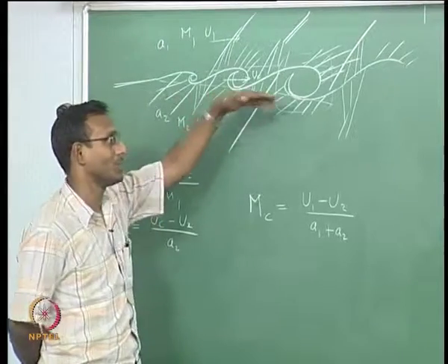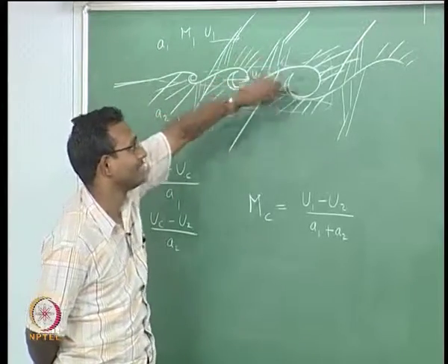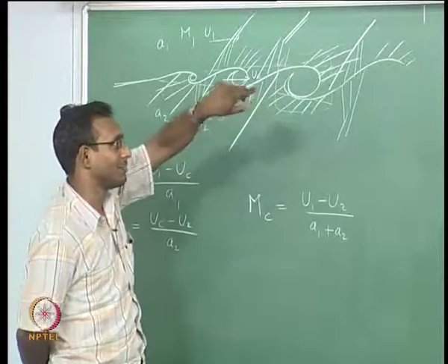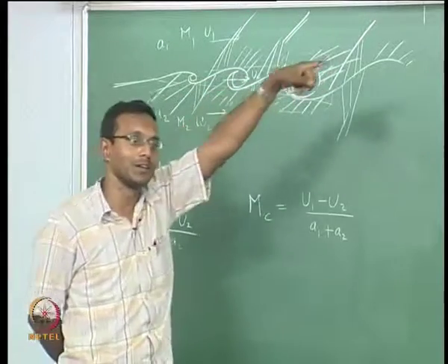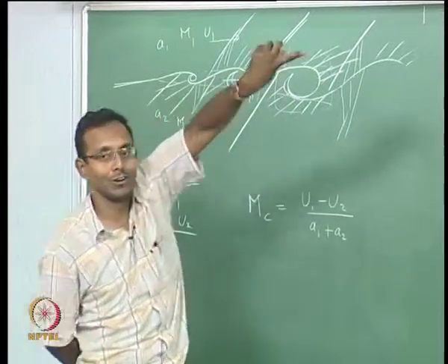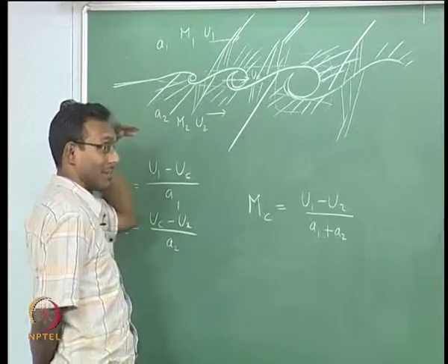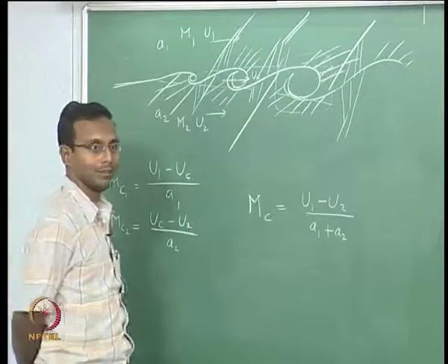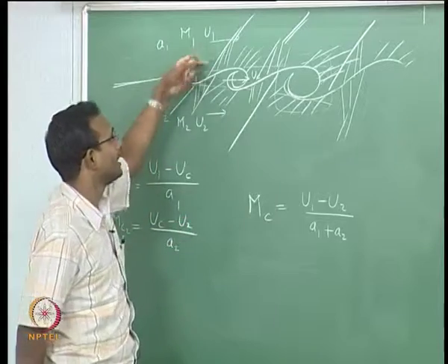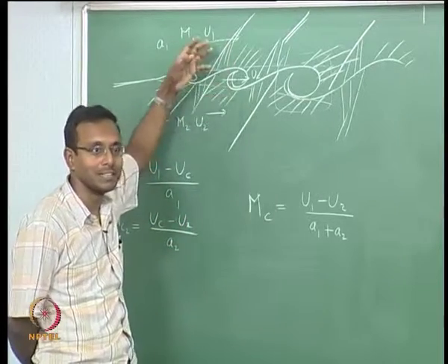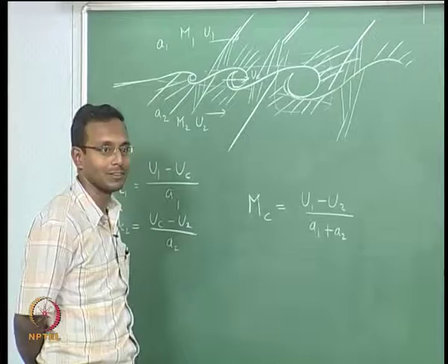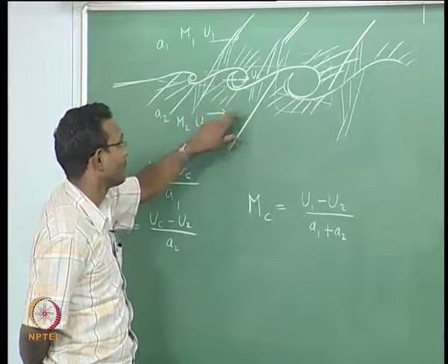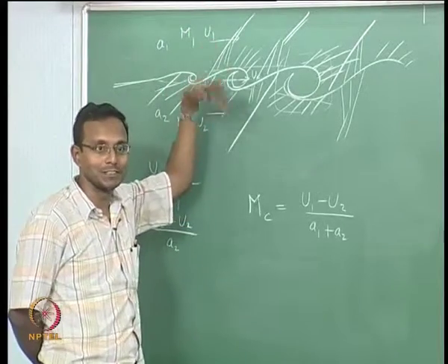With streamwise vortices, there will be rotation like this as they go, and the next one will be rotating the other way, and the next one counterclockwise, clockwise and counterclockwise when I look from the front along the flow field. This is going to help in mixing. This is what they study as the mixing layer in supersonic flows. It takes the bottom fluid up and the top fluid down and mixes them.